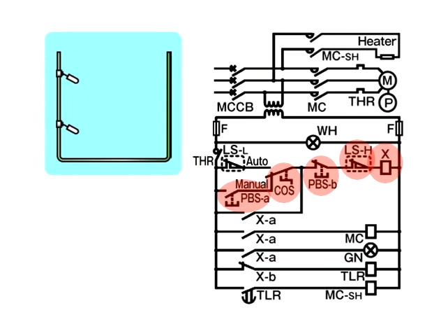As a result, XA is turned on, and the current begins to flow from XA to PBSB, LSH, and to X. Therefore, even though the finger is removed from PBSA, X continues to be excited. This state is known as the self-holding state of X.